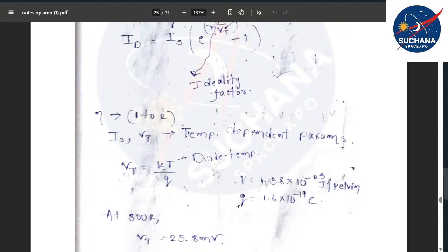Here we are discussing how to use an op-amp for performing logarithmic operations. In logarithmic operational amplifiers there are two categories: temperature non-compensated and temperature compensated. I don't say temperature independent, because a diode is always dependent upon temperature.